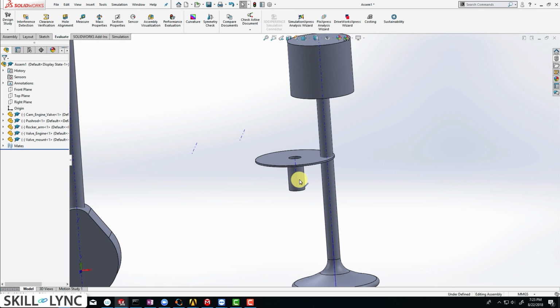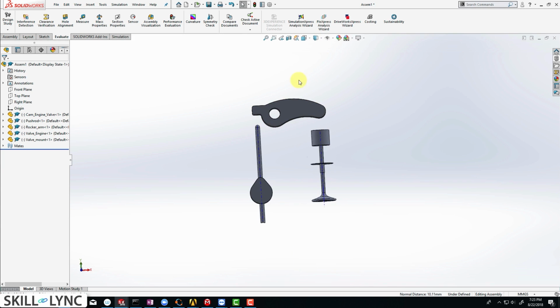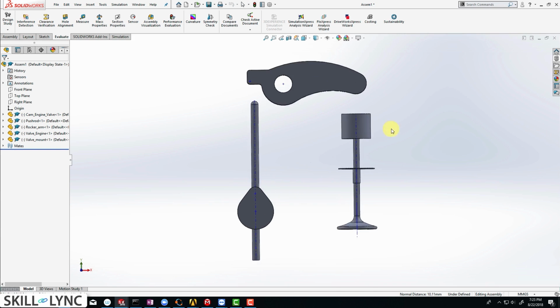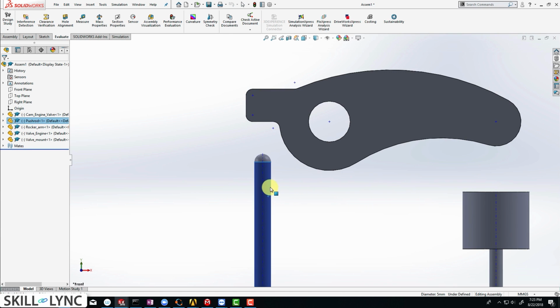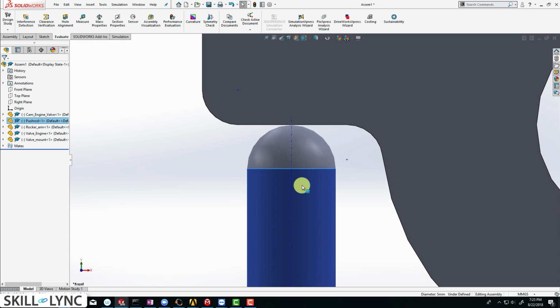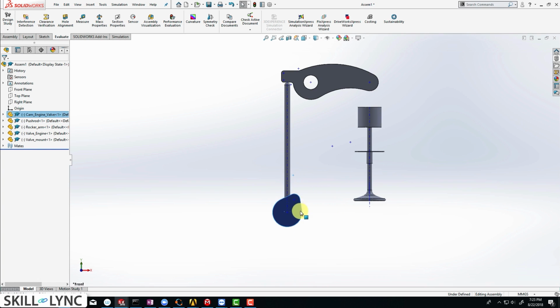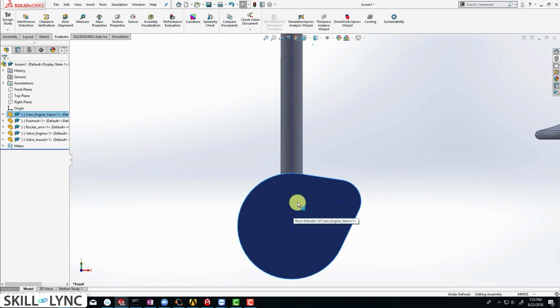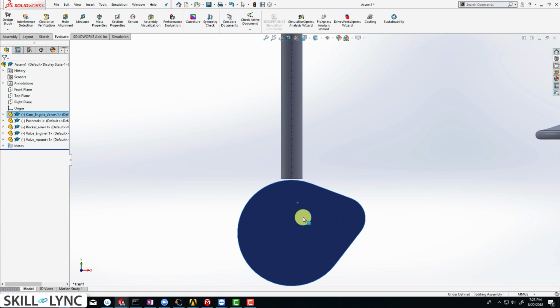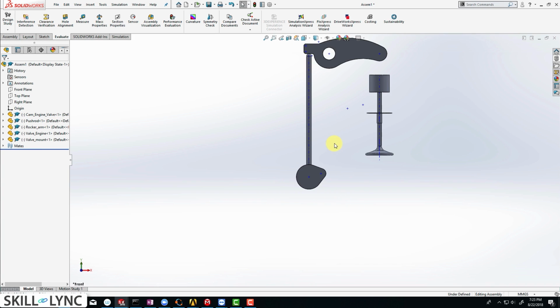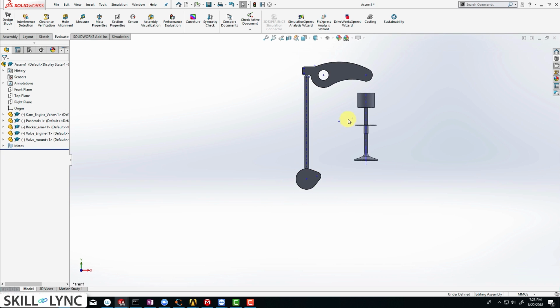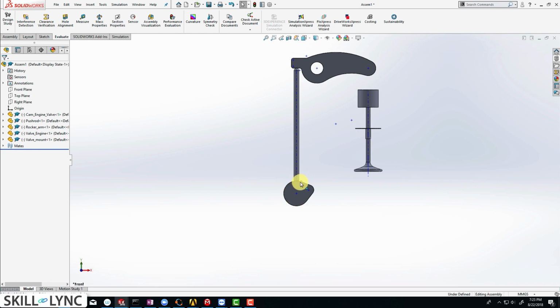So now you can just drag out the valve and we should be able to coincide these two axes. So let's select axis number 1, axis number 2, make sure Control is selected and click on make coincident. Now let's take a look at the geometry from the front plane, and let's just click on this and push it. Because of our constraints, it's going to perfectly move in the vertical axis. Similarly, we should be able to rotate the cam and drag it exactly vertically down. Now we are manually setting up the position, so make sure that you see a very small gap, right?